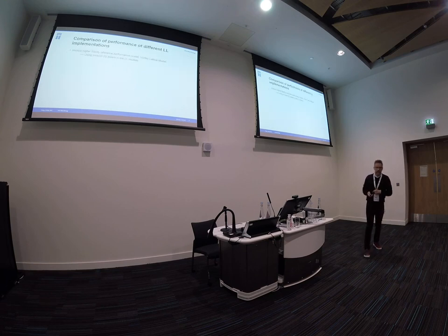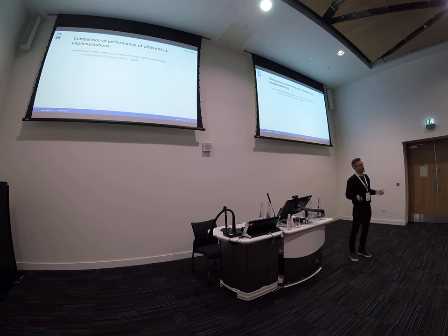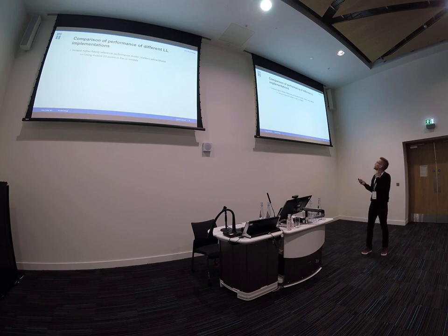Okay. I want to compare to something. My truth will then be something I know well. I'm doing a vortex lattice solution of the same geometry. And then vortex lattice corresponds to it. If I do that in 2D, I get an implicit lift polar. So if I'm comparing towards this lattice method, I input in the lifting line method a 2 pi alpha lift slope and 0 drag. And then I should be able to compare the results.